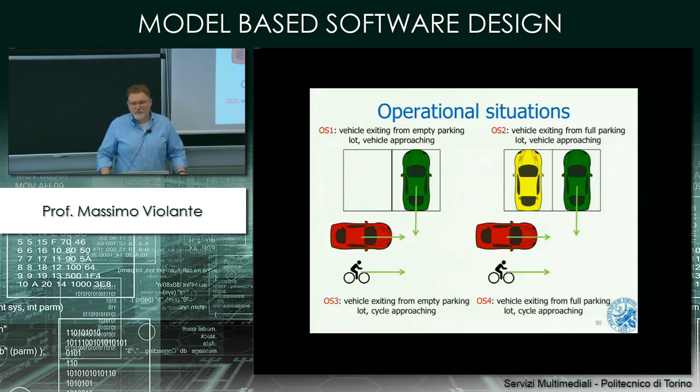This is a rather valid operational situation. But the question is, does the item apply in those operational situations? So you can have the item that starts working giving you false indication of an approaching vehicle on the back when you are driving forward on an empty road. This is QM for sure, because nobody gets hurt by that kind of failure.